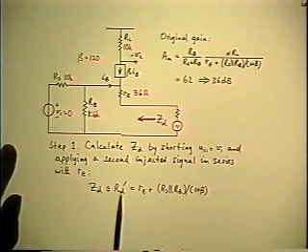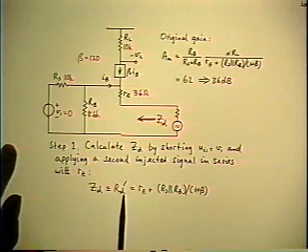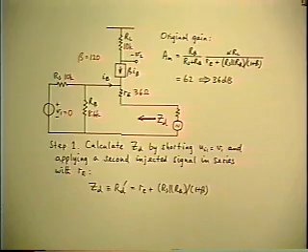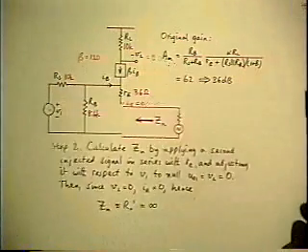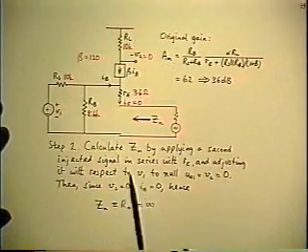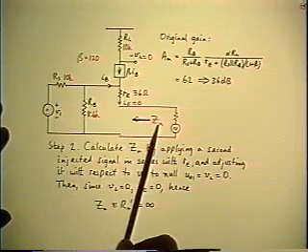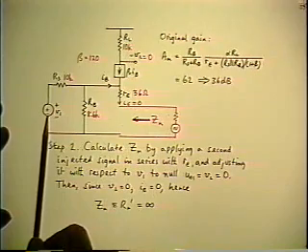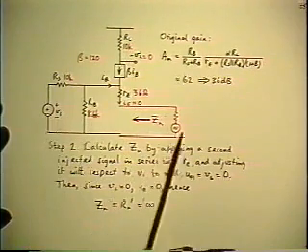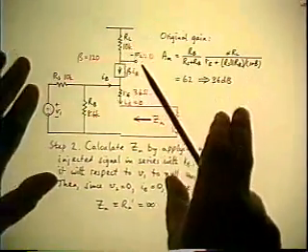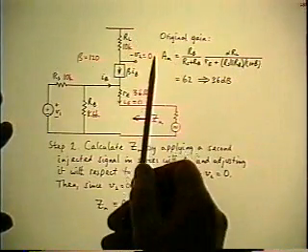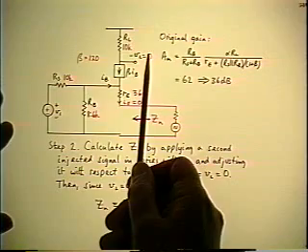I've called it an RD prime this time because it's a different calculation than the previous one. So that's easy enough. The null double injection calculation. Apply a second driving source and restore the original source. So it's double injection. Imagine that you've adjusted the two sources in magnitude and phase until you null the first output.